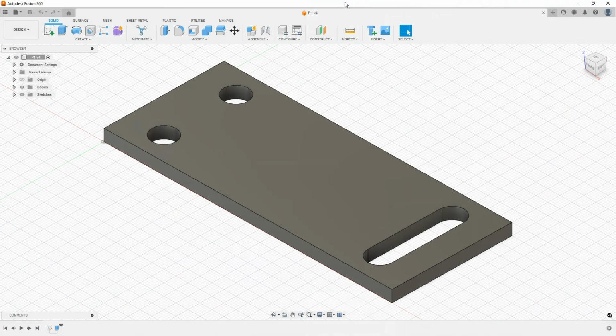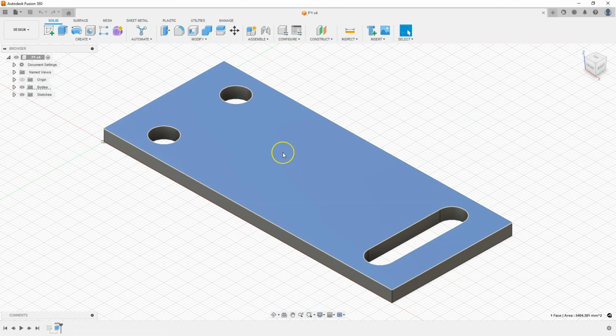Let's create the next stage of this 3D solid, and as before, we will create another 3D solid part based on the 2D sketch. Apart from that, we can create sketches on the basic work planes of the coordinate system, on the XY plane, XZ plane, or YZ plane. We can also create sketches on the faces of the solid. To create a sketch on a model face, left-click on the face on which you want to create the sketch, and then select Create Sketch.